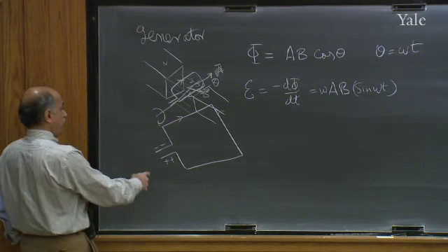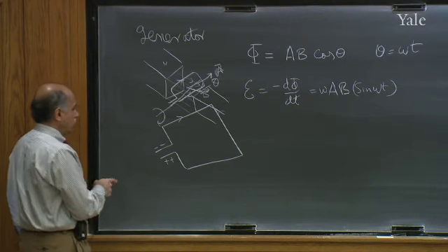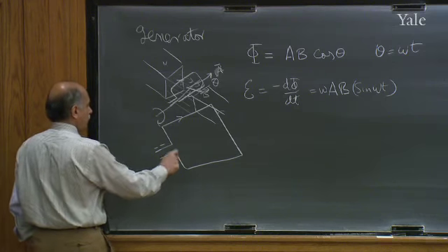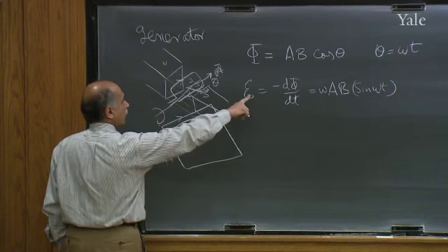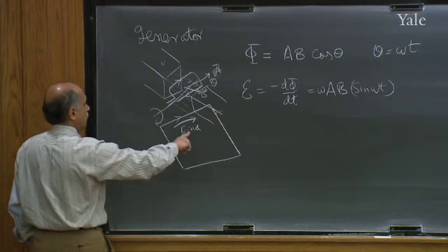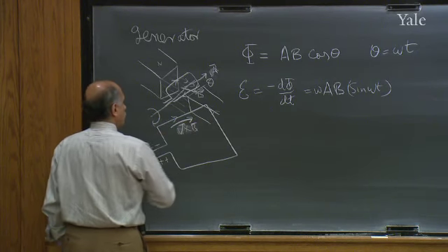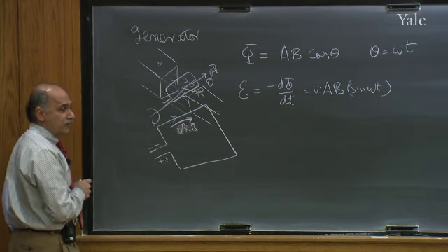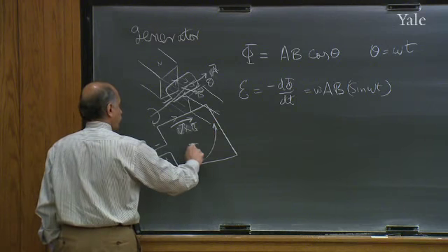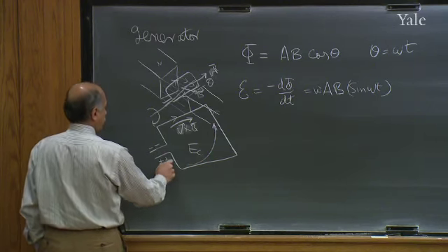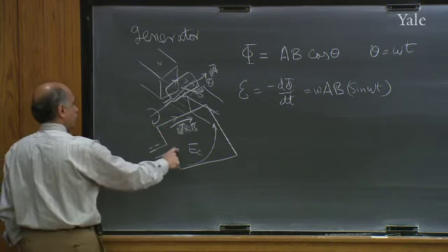But they cannot go very far because it's an open circuit. At some point, these charges have piled up here. So this is the induced electric field obeying that equation. This, in fact, is not an induced electric field. This is just the v cross B force on the charges. But then these plus charges will produce an electrostatic force, called the Coulomb field, which is the electric field due to charges, which will oppose it till the two cancel inside the wire.